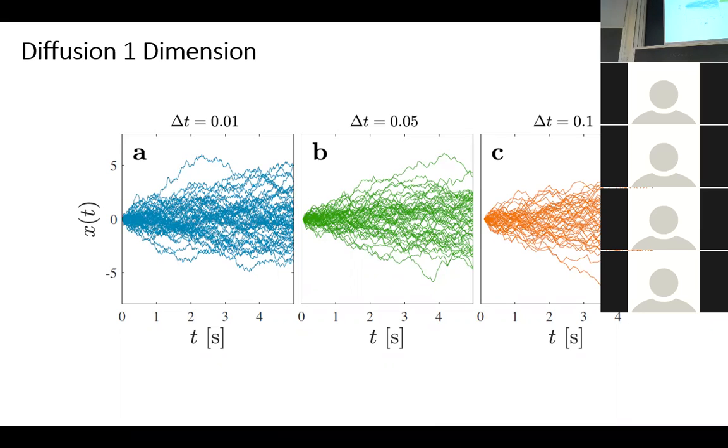If you don't scale, they are going to displace a lot larger than these ones. The overall displacement of the particles is going to increase with larger delta t. And it won't be consistent. Whenever you change your delta t in your simulation, you will get different results. This is something we absolutely don't want.